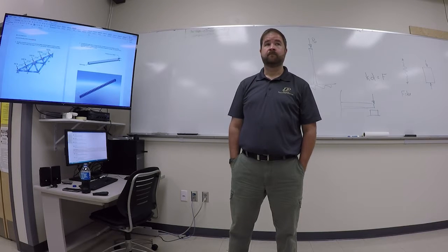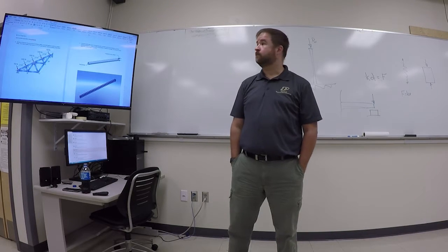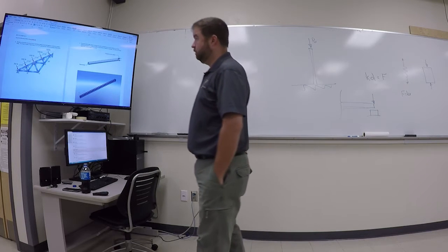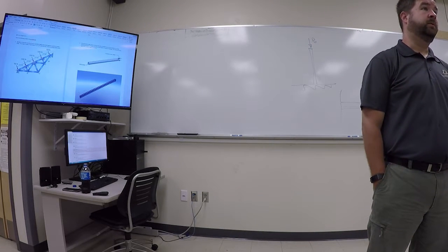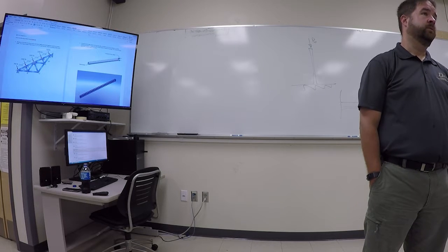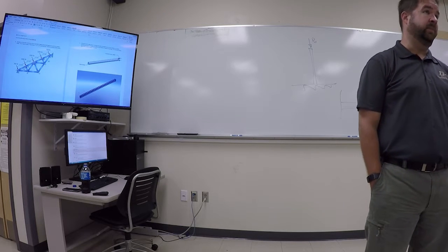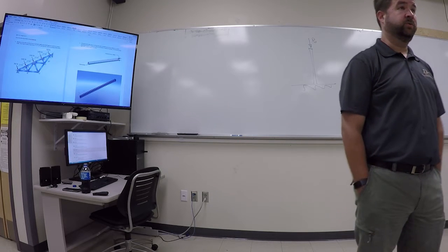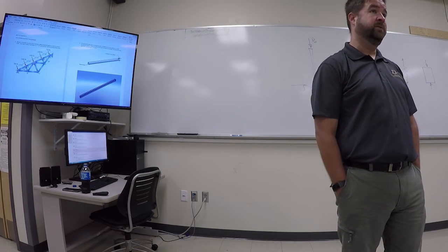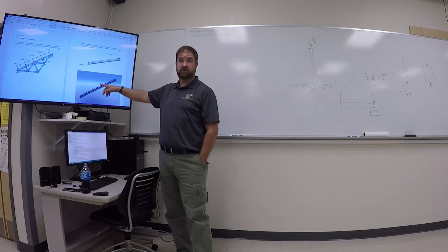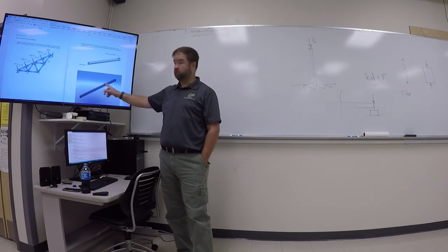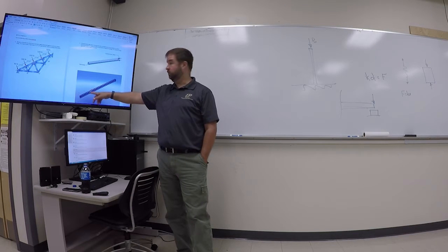When we do these, do we use a mesh or is it a shell? I would think you do a mesh, but well, mesh is not a type of element. For some of these previous ones, for the static ones, they had an element type, but for buckling, it's different. But you can use any type of element type. For the truss, you've already modeled that as beam elements, so I would leave it as beam elements. This one, I think you need to use shell elements. This is thin, this could be represented easily as two-dimensional flat plates, right? So I think shell elements would be appropriate for this one, if that's what you're asking. Yes.